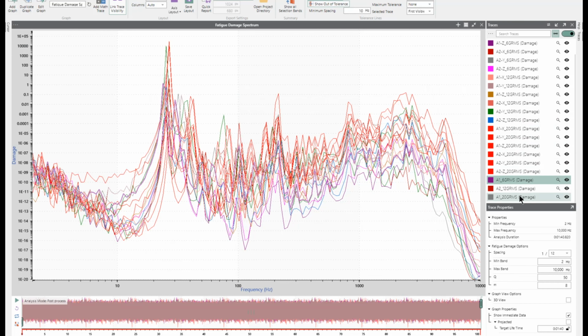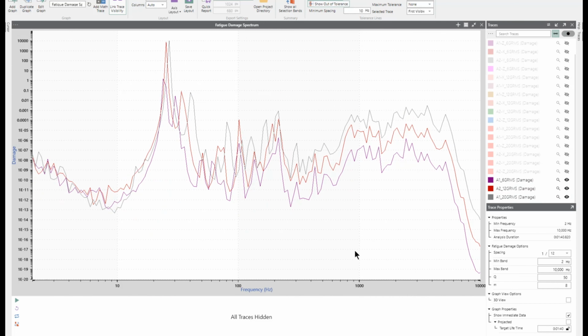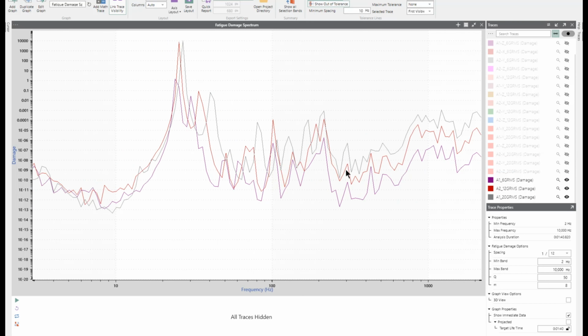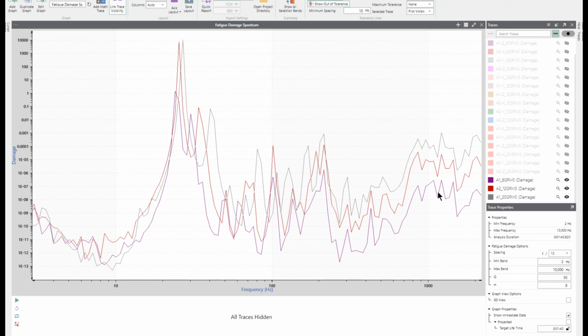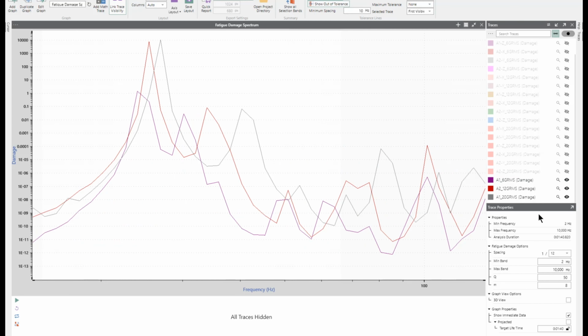So now, if I look at just these three, what we're looking at here is this shift in overall excitation frequencies, especially in this lower band. Once you get into the high frequency band, especially because we're looking at things as a log-log function, this differentiation gets pretty smeared and stays together because your frequency bins are much closer together. At these low frequencies, though, we can see the difference in the excitation frequencies.